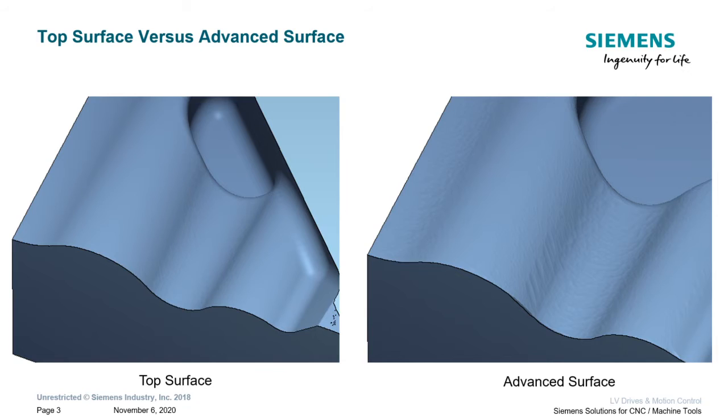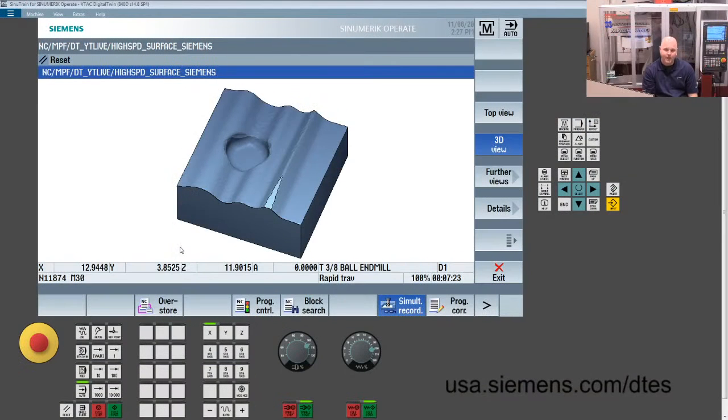Generally that's always a case where the point distribution cloud of the toolpath coming out of the CAM system wasn't consistent. As we were going back and forth, because I did do a bidirectional toolpath cut, I got scenarios where the computed spline could have caused an overcut or undercut. So here again, just showing that we can start to look at a lot of the details that I would normally have to do during first article down on the floor. I can start to look at them right here on my PC.